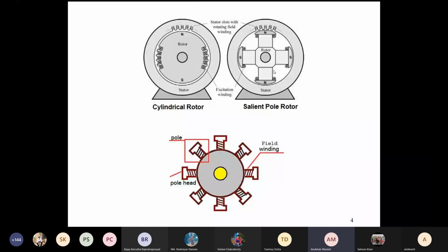No, see, there is always the probability of flying out any time because they have to be mechanically fastened. But if the magnets also attract each other, it will be easier. It can go up to higher speeds then. No, but you see, if it is north, the adjacent ones are basically south. The adjacent ones are basically south. So there is an attraction also.